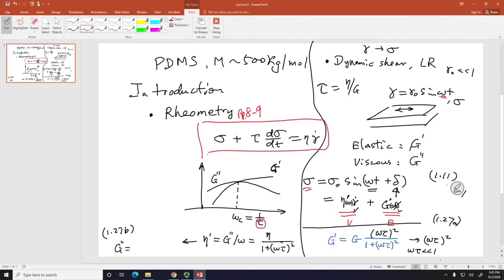If anything, this is the tool. Anybody who goes to a rheology lab, typically, if they are not studying the science of rheology, is there to use this to characterize, and one of the most crucial characterizations is to learn about the internal time scale, the internal relaxation times. For example, this PDMS, now you see it's getting flat. I can force it to change shape because it's not cross-linked, and force it to change shape any way I want, including doing it very fast and breaking it too. We will describe all this in much more detail in the future.